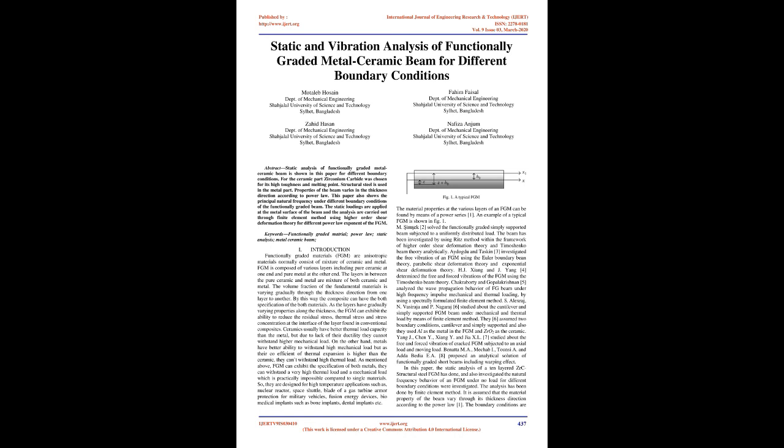The static loadings are applied at the metal surface of the beam and the analyses are carried out through the finite element method using higher order shear deformation theory for different power law exponents of the FGM. Keywords: functionally graded material, power law, static analysis, metal ceramic beam.